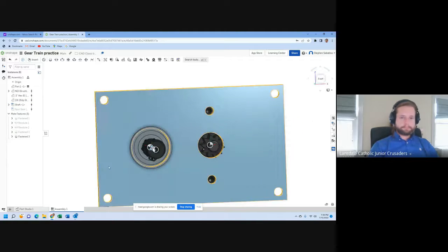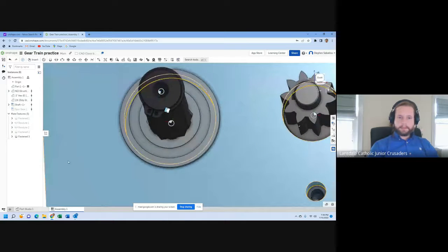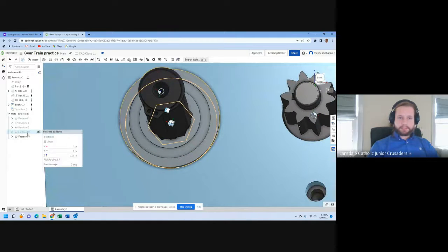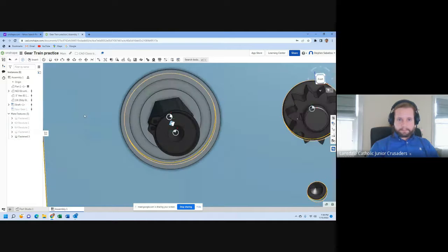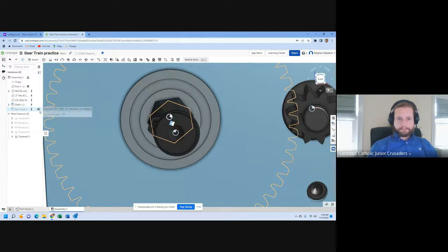Yeah. See? So right click on the bearing and hit show mates, or if you know which mate it is, then you can do it that way too. This one. So edit that. You can right click edit or you can just double click. And then yep, there you go. That's it. Oh, beautiful. There you go.